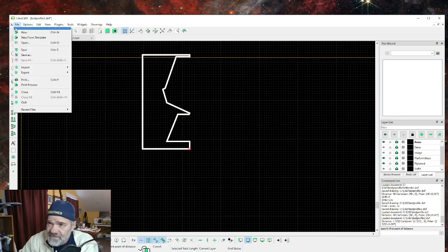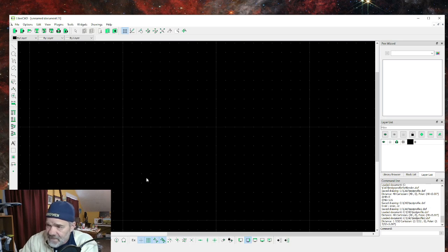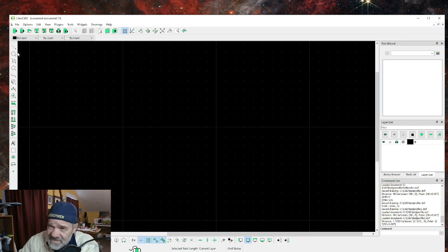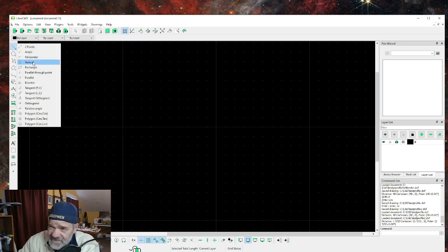Let's do a file new. Okay, and let's say I can come up here to options, and I have all of my measurements in inches. Okay, and you can use decimals. If you're imperial, this is a big deal. If you work in metric, this stuff doesn't matter to you. Okay, but you can do decimals and all that kind of stuff. All right, so I'm going to leave that as decimals, and let's do some of this CAD functionality.